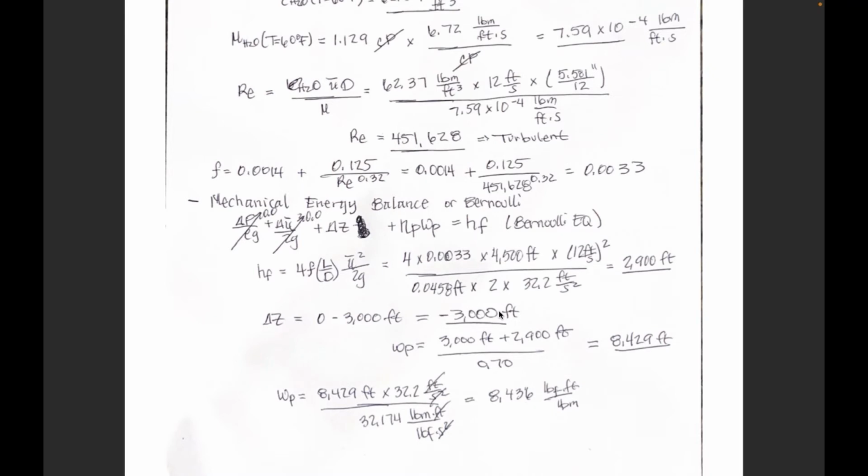for the equation that I was talking to you about previously. The mechanical energy balance, or the Bernoulli equation. It doesn't matter what you use, really. At first I was going to use the mechanical energy balance, but then I decided, why not just use Bernoulli? There's an energy form, a pressure form, and the feet form, called head form. And I use the head form on this one, it looks like.